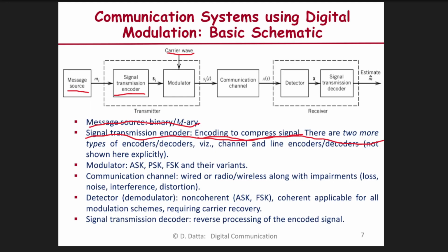encode the signal. It will have almost the reverse process. Here, if there is a binary 0, I am giving you a very crude example, we'll talk about it later. Suppose you are transmitting a 0, and there is noise added to this, so it becomes 1, or there is a 1 you are transmitting and noise is added, and 1 becomes 0. But if you transmit 3 zeros instead, all 3 zeros becoming 1 is least likely.